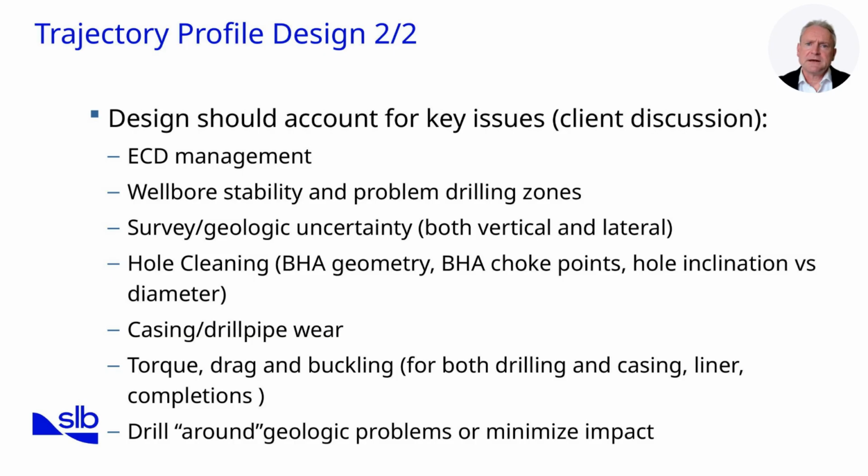This slide expands on trajectory design considerations, showing the wide range of factors that must be addressed. ECD management is one. Trajectory choice influences circulating pressure, especially in long high-angle sections. Wellbore stability and potential problem zones must also guide design. If unstable formations are present, the trajectory may be adjusted to minimize their impact.